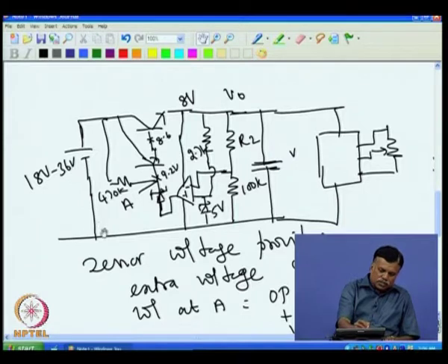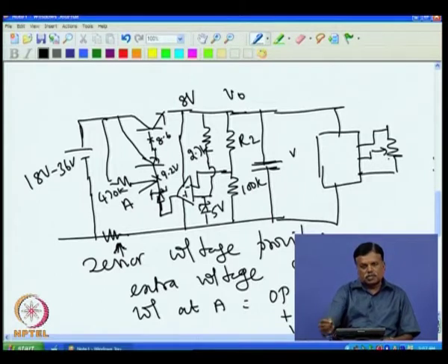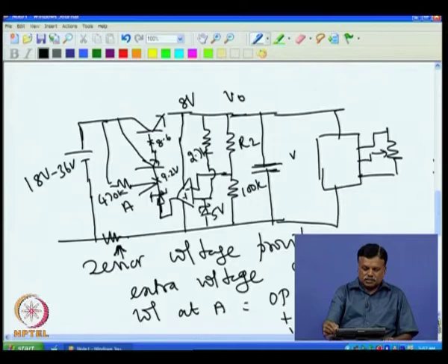In actual use they will be using the on resistance here to measure the current, and that current should give the position information corresponding to this potentiometer. So, since the voltage across this is now constant, this receives a constant voltage. Now this current transmitter can be designed easily. Let us see how to design this current transmitter.